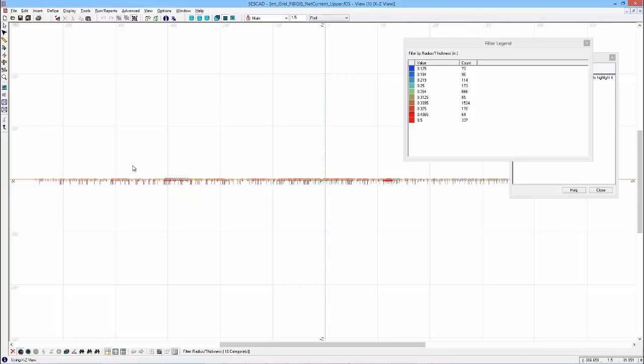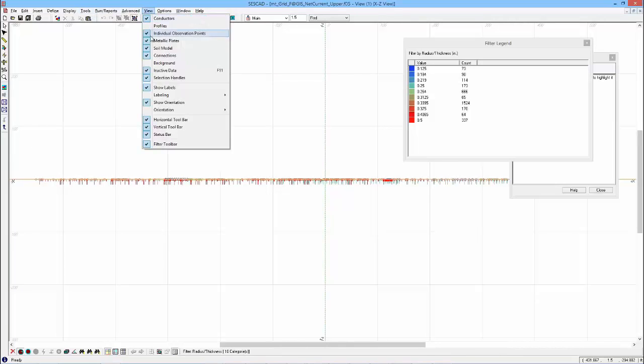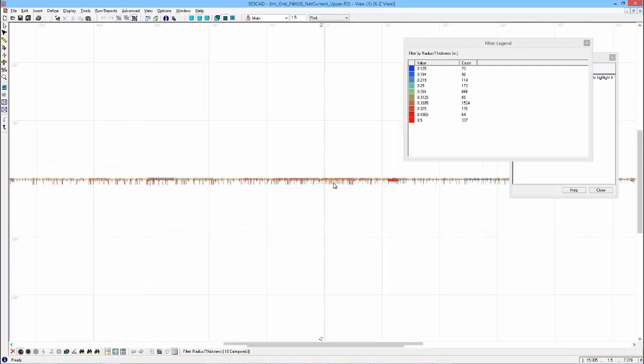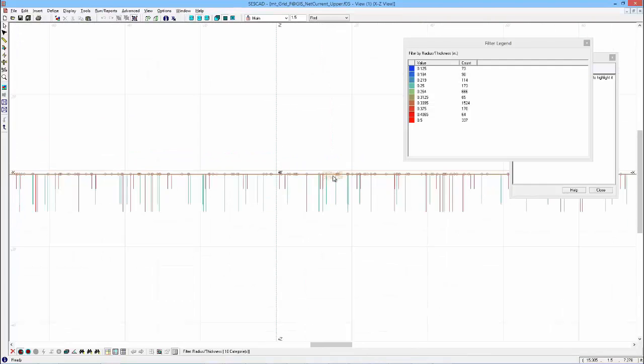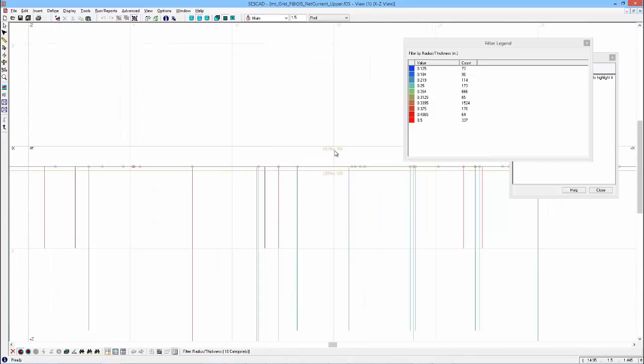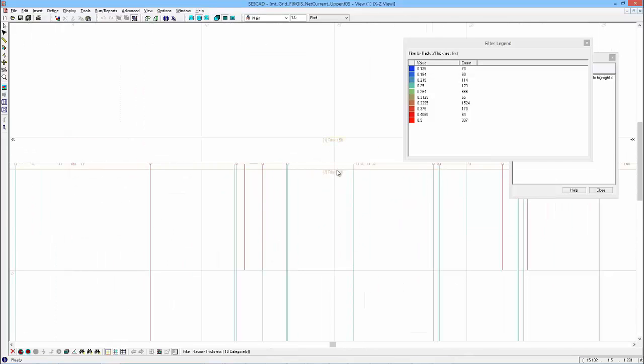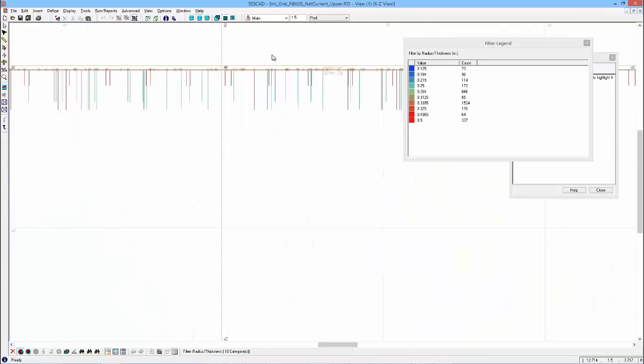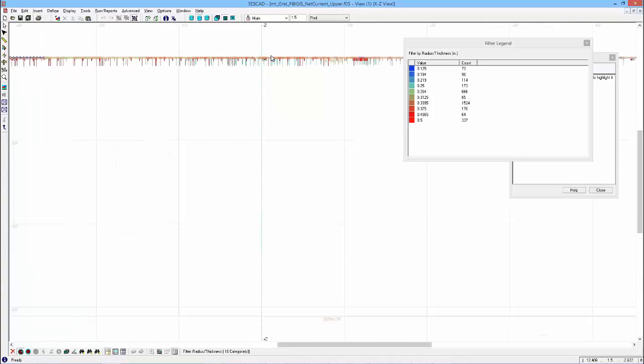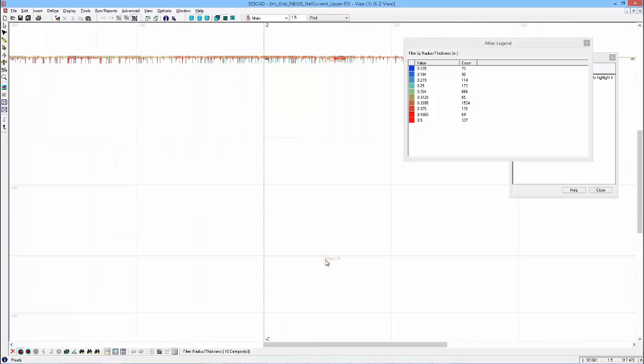Taking a side view again, we can see how the soil model and our grid live together. So let's label the soil data. We can zoom in here. And so we see the top layer of 150 ohm meters. That includes actually a majority of the grid conductors. But the rods penetrated to the 320 ohm meter layer. And far below, we see our 90 ohm meter bottom layer.